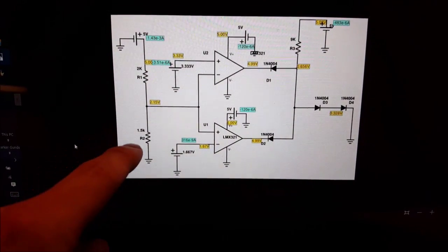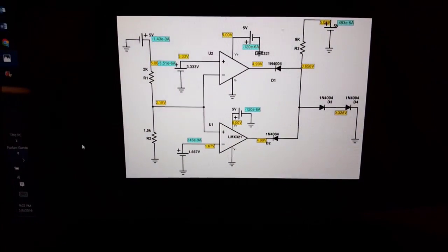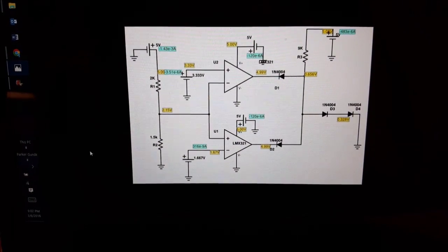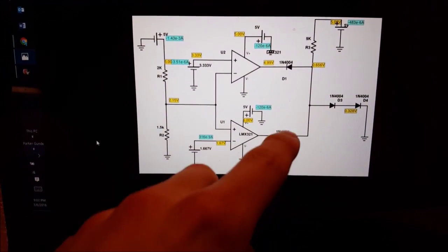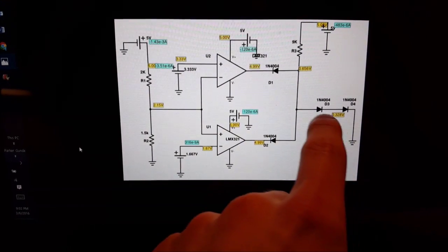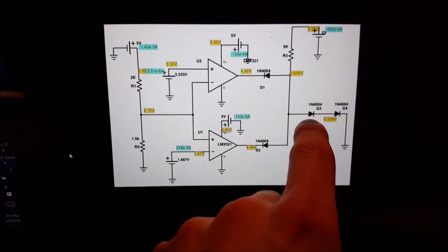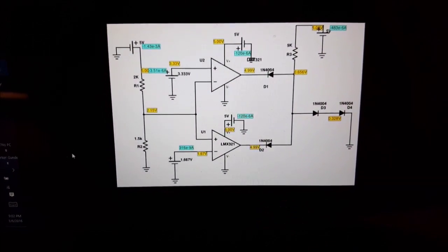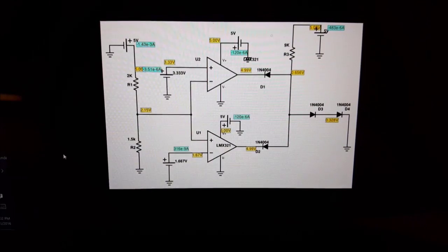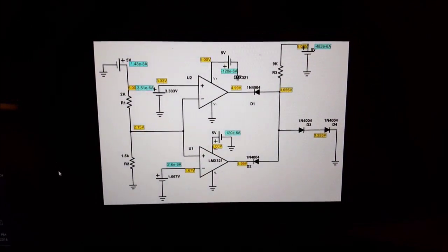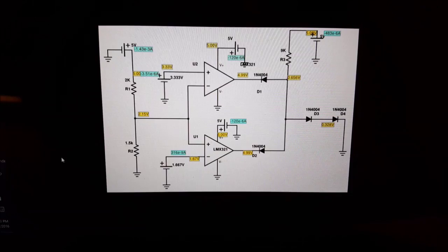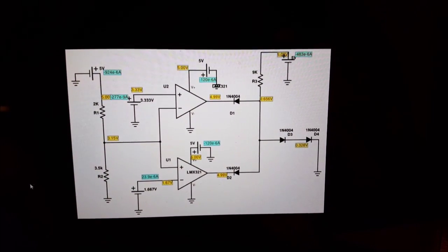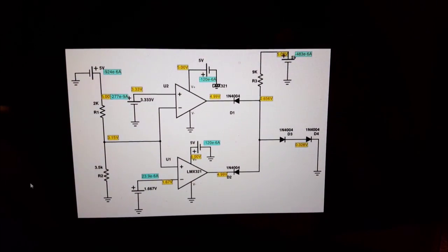Here's the second situation. This is just dropping below that 100 lux, so we're inside of our range for having output, and that happens according to the min function. Both of these should be off. Both of these should be on, and current going out should be about 400 microamps is what we're aiming for, and this gets close. It gets 480 microamps.